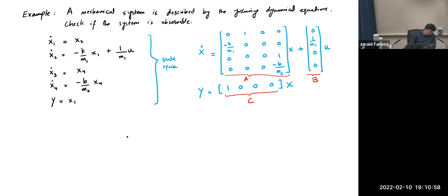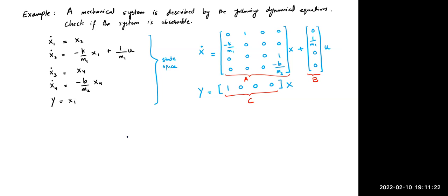But that's a good question. You should be careful that it's not like D doesn't have any role in the system, but it's like a feed forward kind of gain, which a lot of the time doesn't really matter. So when we talk about feedback control systems, A, B, and C are the most important matrices. Okay, thank you.